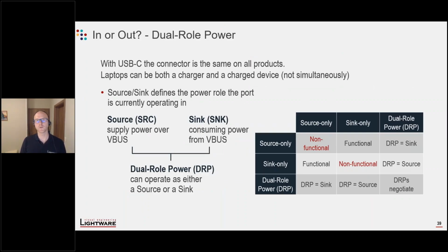And another interesting feature of USB-C and powering is that many devices are called dual role power devices, or DRPs. That means that the USB-C port on a MacBook Pro, for example, can accept charging. So that's how you connect the charging brick that comes with the MacBook. But you can use the same port to power a peripheral. Let's say you want to charge your phone or your tablet or maybe an external hard drive. In that case, the USB-C port can output power.